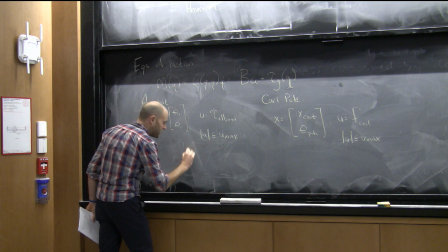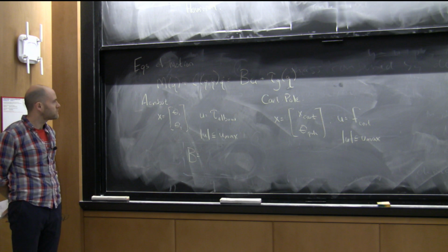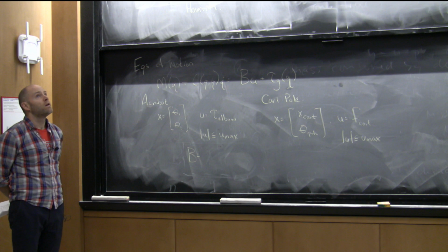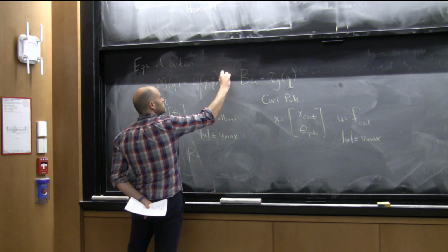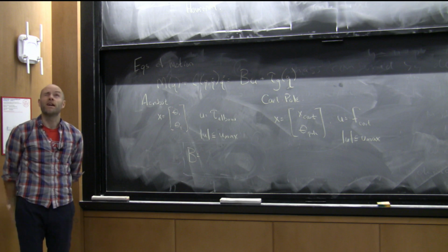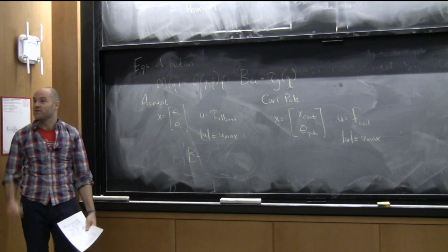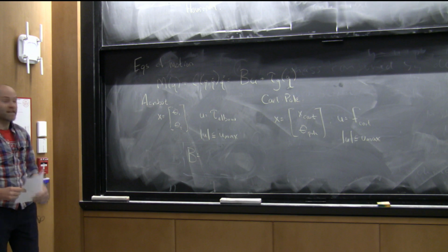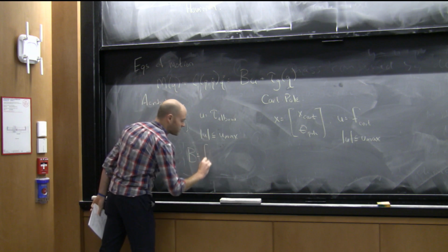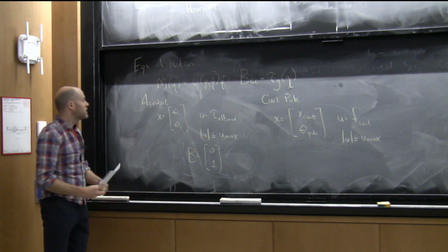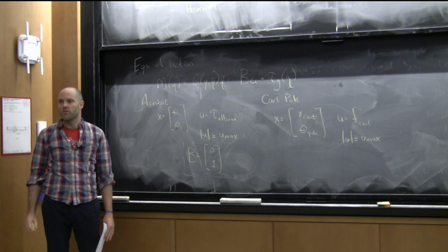Okay, so what is the B matrix for the Acrobot? It's actually a really hard question if you haven't thought about rigid body mechanics before. The torque is between the two links, in the relative frame. How does that relate to the generalized coordinates that we use in the equations? That's tempting, but it's actually not. Because it's a torque against the second link, it turns out to just be 0, 1. If theta 2 was the absolute coordinate relative to the upright, then I would get something like negative 1, 1.